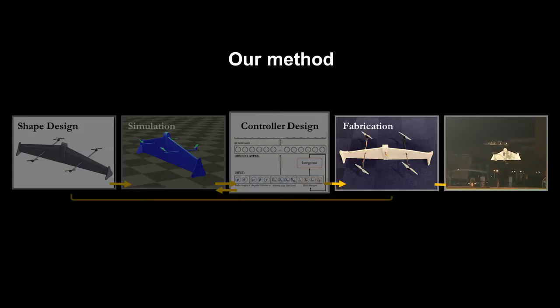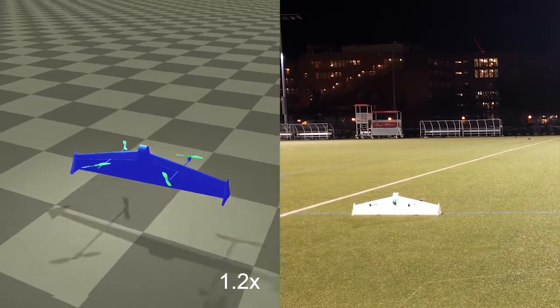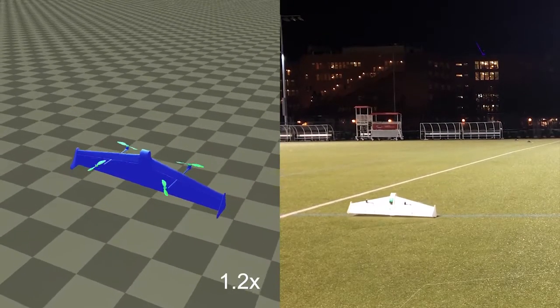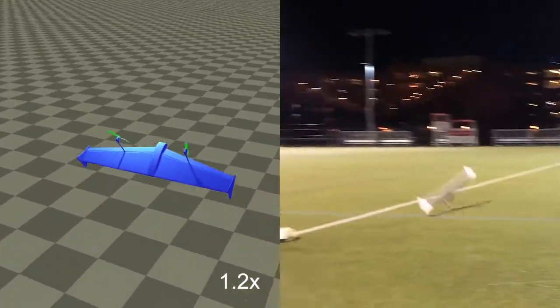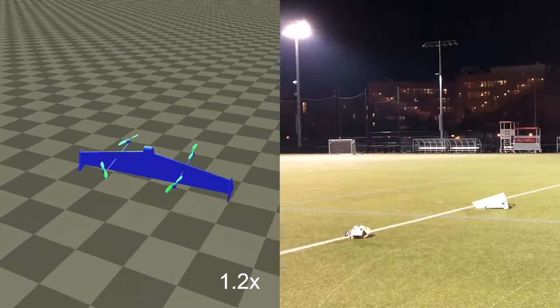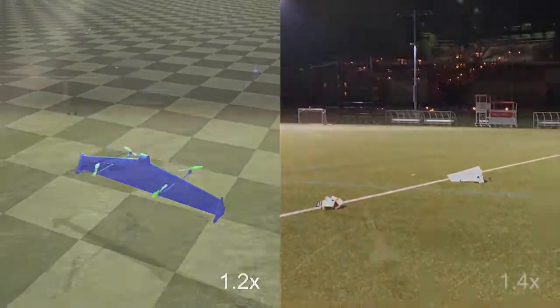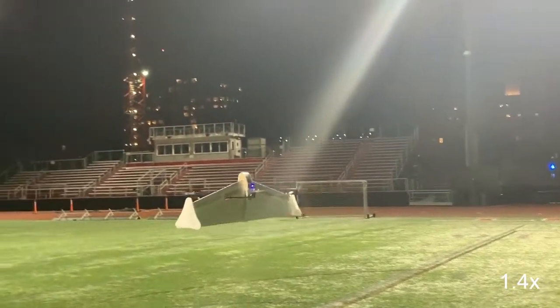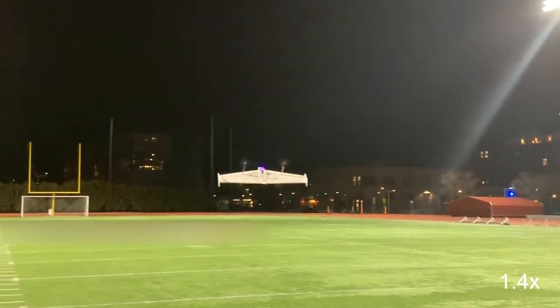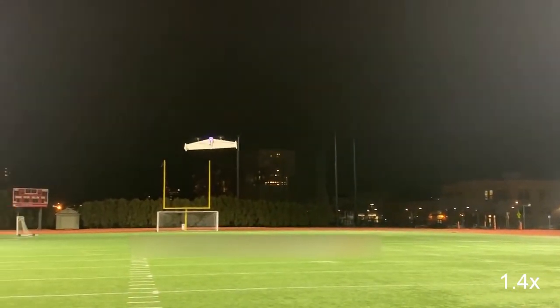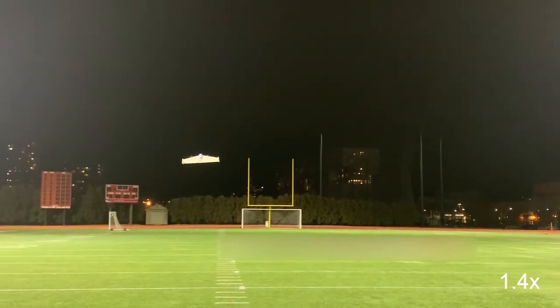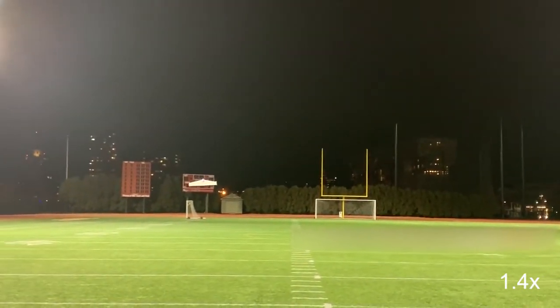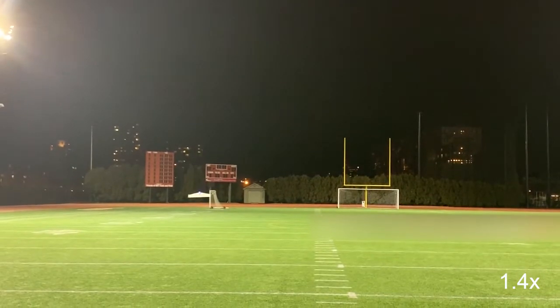Once we trained the controller, we deployed it on hardware to verify its robustness. Because of the reality gap, a naive controller without our proposed modifications crashes catastrophically when implemented in real hardware. After incorporating the integral block and orientation cost proposed in our work, our trained controller was capable of finishing the flight task successfully. Our controller design generalizes to hybrid UAVs with significantly different dynamics.